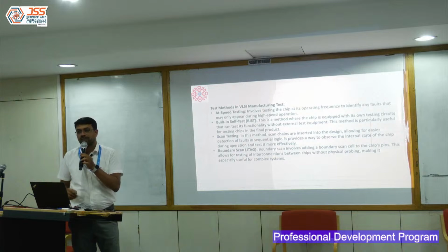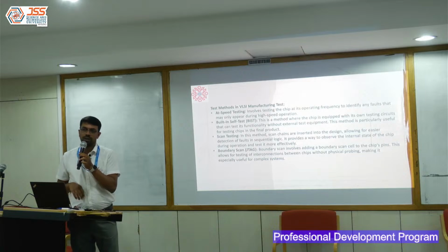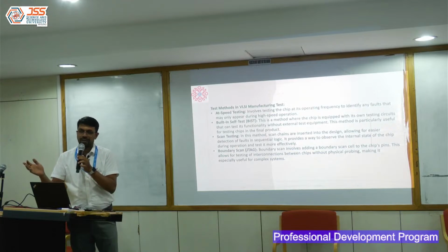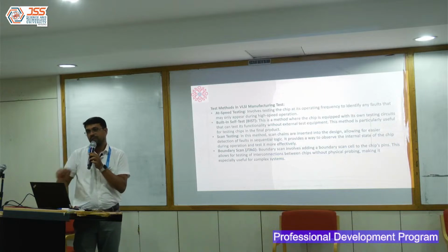What is setup violation? Setup is the minimum amount of time the data has to be stable before the appearance of the clock edge. Clock is in my control. If I reduce the clock frequency, your pulse or the clock width will increase. So you can delay the clock, right? And give that additional time for the data to settle down. So I can obviously work around it.